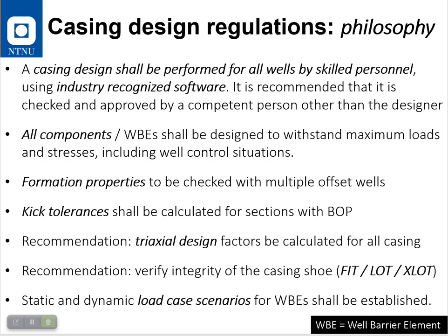Casing design shall be performed for all wells by skilled personnel using industry recognized software. All components in the well barrier elements shall be designed to withstand the maximum load and stresses. And again, remember, what would be the maximum load and stress in any situation for any well?